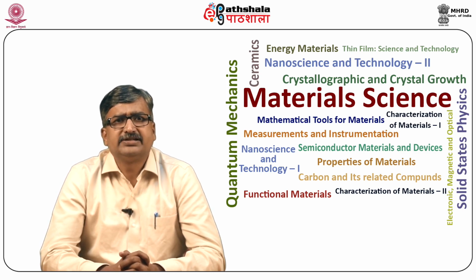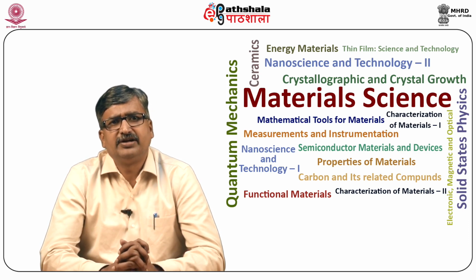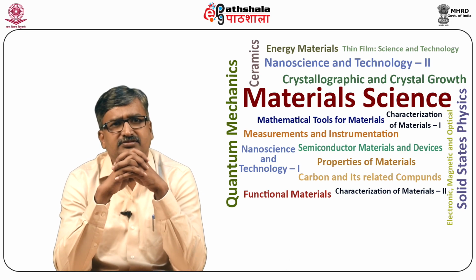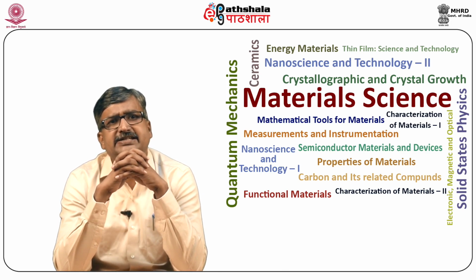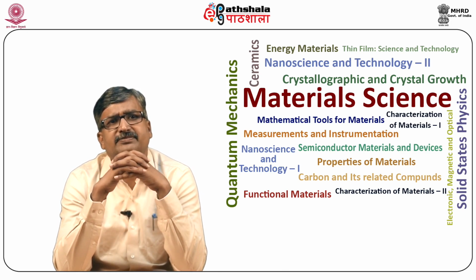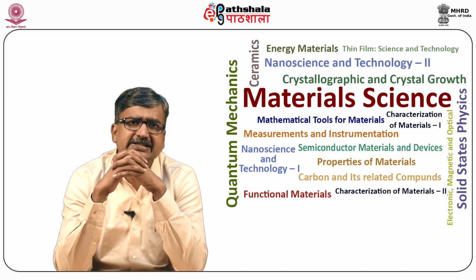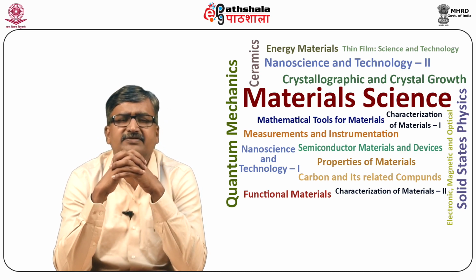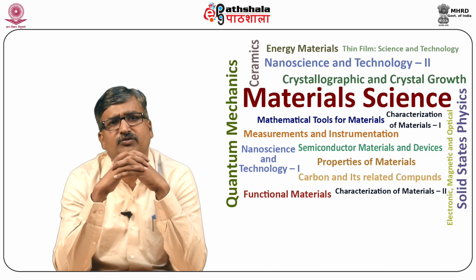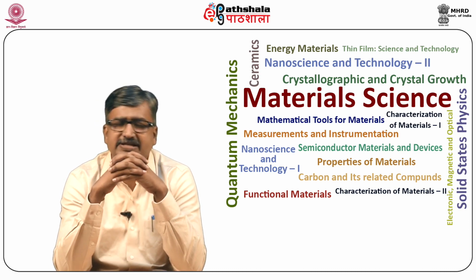There is a failure mechanism of conventional grain size material, mainly governed by cracks and dislocations. A crack is essentially a region of the material where there is no bonding between adjacent atoms of the lattice. Dislocations are essentially regimes where the lattice deviates from the regular structure, extending over a large number of lattice spacings.